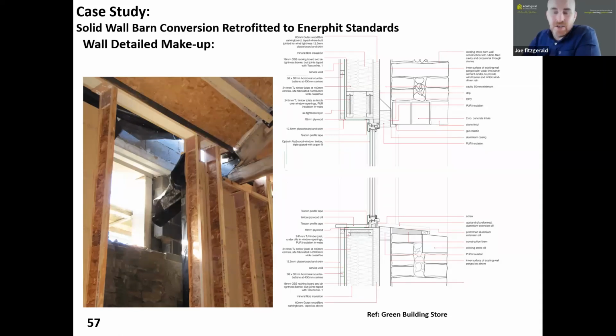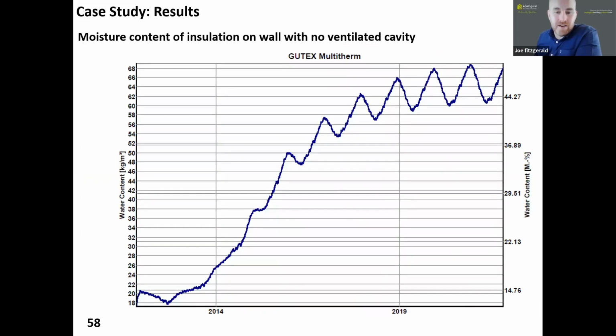That was the key question, because to perforate that building in multiple places would have meant using air bricks, cost, time, labor, et cetera, et cetera. So they really needed to look at this from a point of view of moisture risk. So from that point of view, we did look at it. And with WUFI, we modeled it. And what we did was we put a probe on the back of the wood fiberboard to see what would go on there, in the model over a period of time.